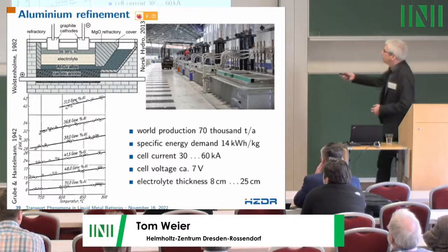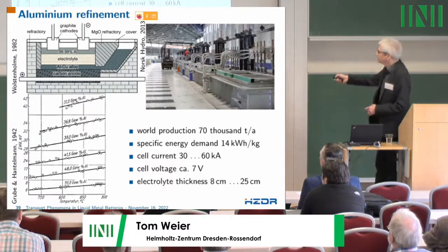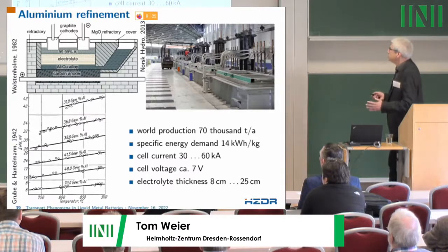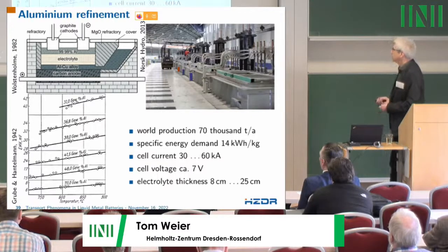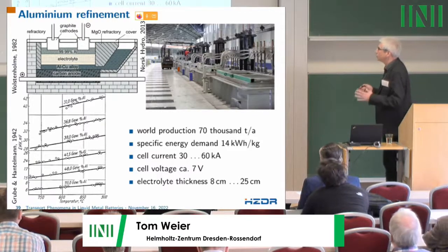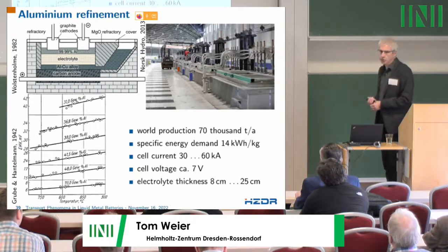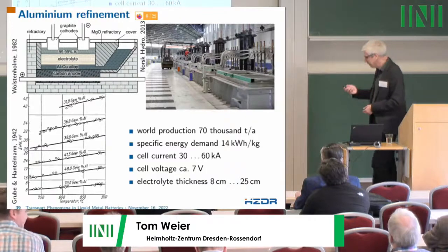It's more pure. But so you have a concentration difference between the aluminum here, the pure aluminum, and the aluminum copper alloy. Unfortunately, the voltage differences that we get are at maximum 40 millivolts. This is not too much, and you have to observe that the electrolyte thickness, for the reasons I just mentioned, is huge. So you will not draw much current. This is not the purpose of the cells, but these are cells that operate at very high temperature, and they are in industrial use for almost 100 years. So this gives me hope that we might see larger liquid metal batteries in future, maybe.